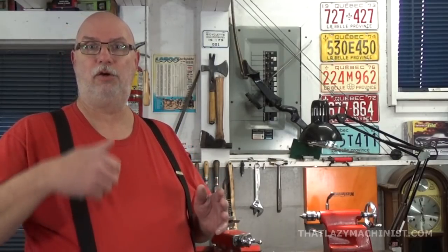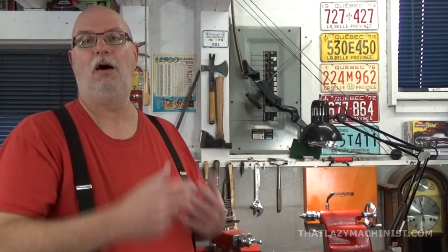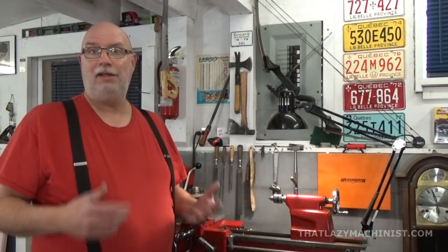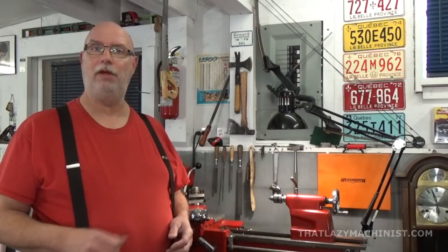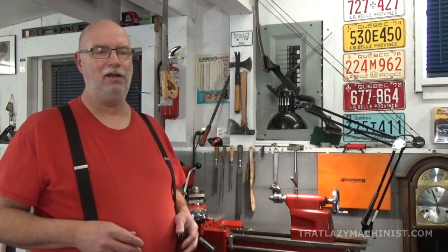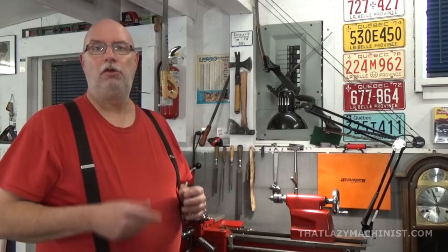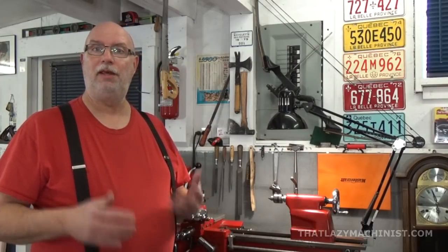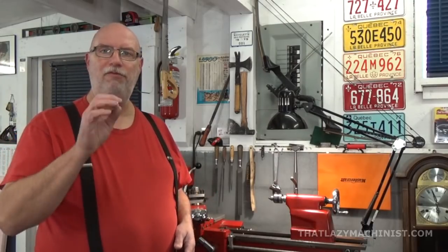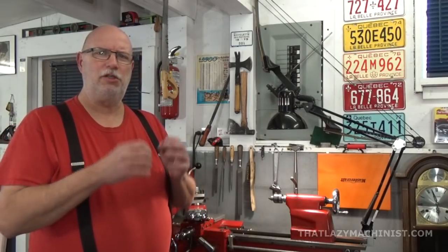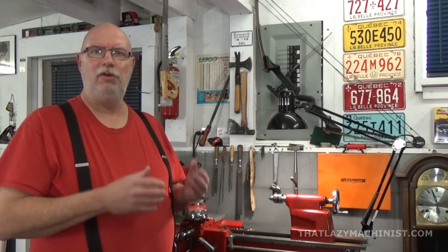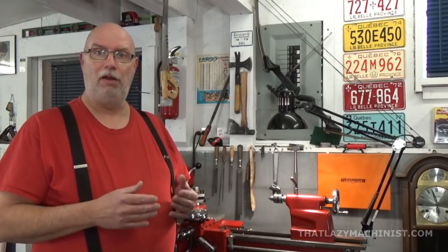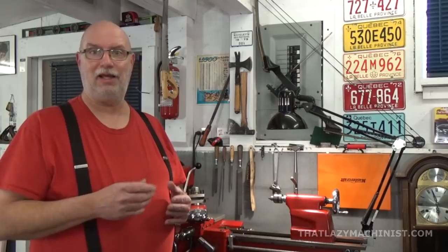And that means that the tool can draw the chip away as it curls off of the part, but the difference in length is going to flip the chip over onto the surface that I've just produced. And since the diameter that I'm producing, the 25/1000ths of an inch, is quite delicate, well, that chip that's flipping over could very well push that diameter off its axis. So what am I going to do? Well, I'm going to take successive cuts, but I'm going to be very careful not to leave just a small cut at the end. We're not going to be doing a finishing cut here. We want the part to be reasonably rigid when I take that last cut.